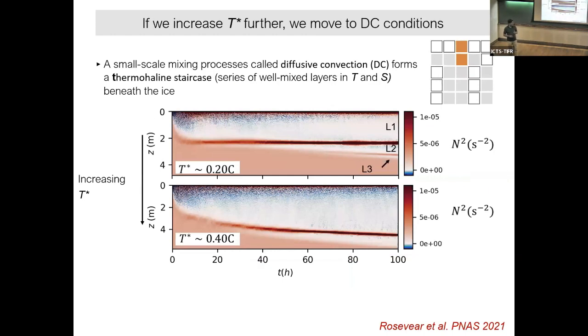Now, another interesting point: the flow is so less energetic that U star is no more important in the problem. What do you expect now? Exactly, natural convection. All sorts of convection are possible now. In here, only one possibility is there, the double diffusion convection, because it's freshwater. When it's the freezing of ice, then it's full convection, because you reject the salt, and ice is also cold. But here it is double diffusion. So double diffusion is very important. For me, I feel like Antarctica is all about double diffusion.